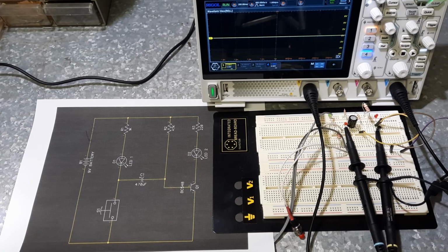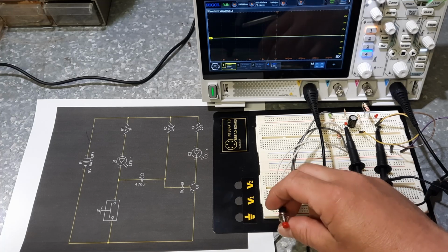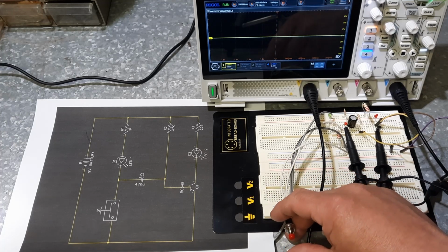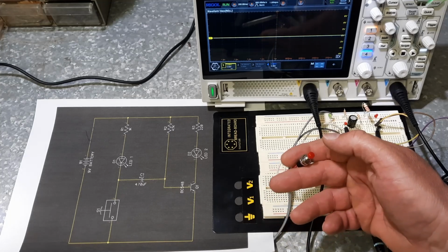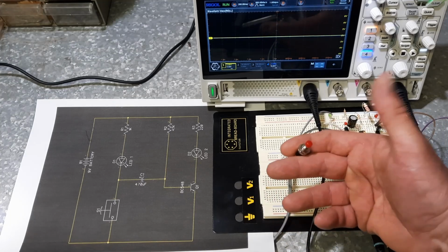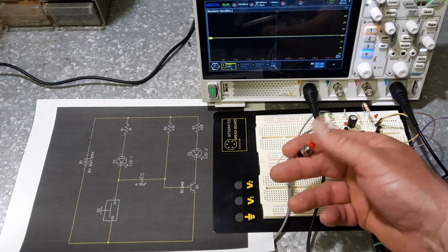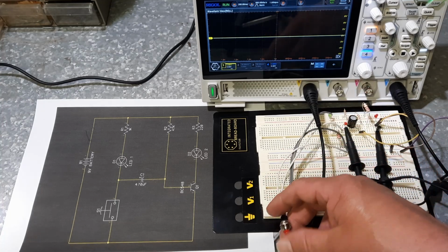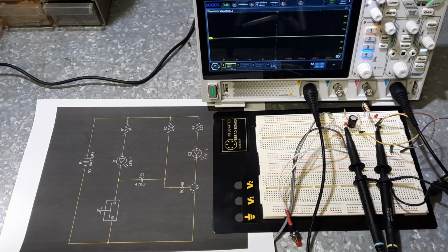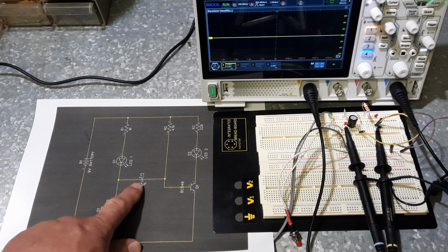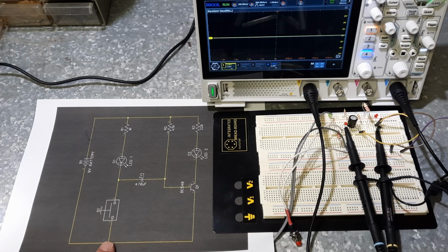So I think now we're pretty much ready to push our momentary switch and make this thing change state. Once again, this is only a momentary switch. It's normally open. If I push it and let go, it'll close and open again as soon as I let it go. So I'm going to have to push it and hold it. But what is going to happen when this thing changes state? So first things first, the positive plate of this cap is now going to be pulled to ground.